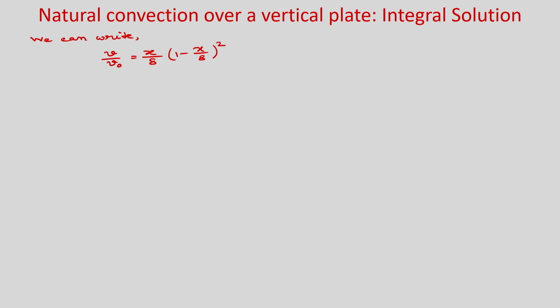Now, you know the assumed velocity profile, and from that we can find the maximum velocity location. So, at which location will you get the maximum velocity? If you take the derivative of velocity v and make it 0, then you will be able to find at which x location you will get the maximum velocity, right.